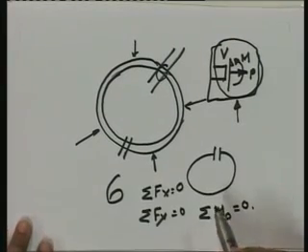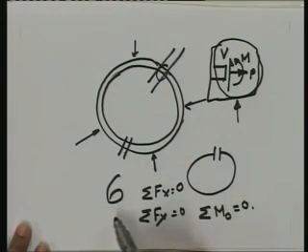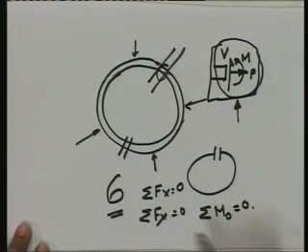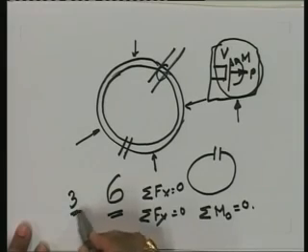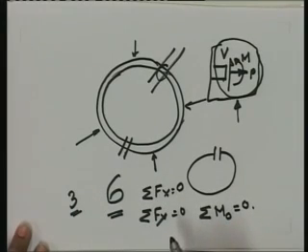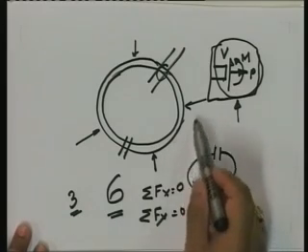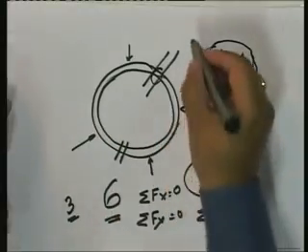These are the 3 equations of equilibrium. So think about it. As soon as I release this and I take a free body, how many unknowns? 6. How many equations? 3. What is the degree of static indeterminacy? Well, number of unknowns minus the number of equations of equilibrium. What does that make it? What is the static indeterminacy of this ring? 3.